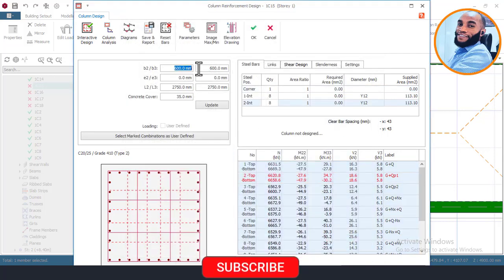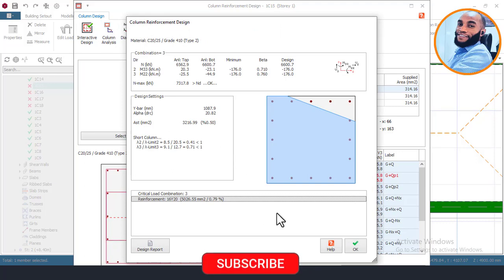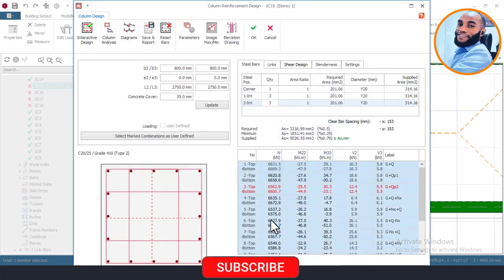Now most people can go and increase their column size to be 800 by 800. Then we set bars and then come here and click on this. It's still okay if you want that. You can see that the more we increase the size of the column, the smaller the size of bars used. But I can see that it's giving me 16 number of Y20. You can see that right now. So you can see that the more you increase your column section, the smaller the bar diameter you use.